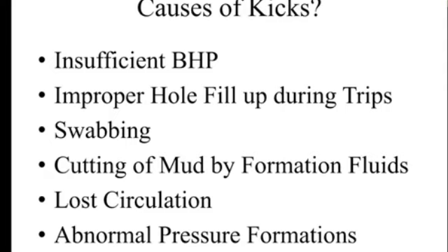So why can this happen? Why does bottom pressure go below formation pressure? There are some reasons here. One of the reasons: if we pull out the drill string too fast, we are creating too much swabbing pressure, so bottom pressure goes below formation pressure.